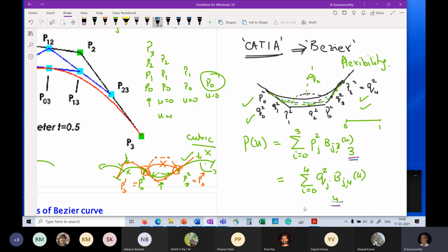Okay. So in the other solution that your colleague gave, we increase the number of curve segments itself. Here, the number of curve segments are the same. I have still 3 segments, but one of the segments now has a higher degree of the polynomial. And we had seen in the first class that has its own baggage of additional effort in terms of computations and number of roots, etc. And therefore that is not desirable. And so that is one of the limitations of the Bezier curve that we are concerned with.